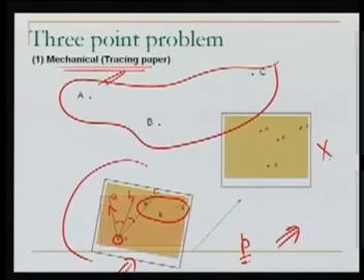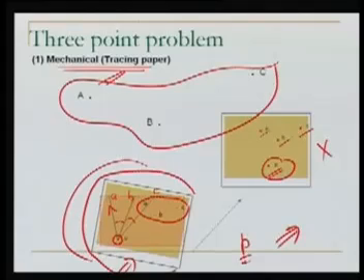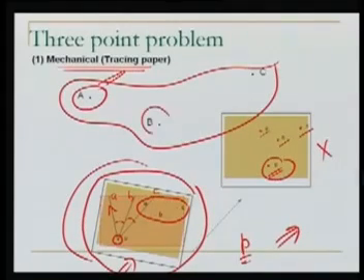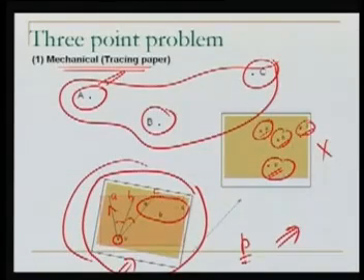We have now A, B and C, which were already plotted on the sheet, and this point P, which we have now found. So basically, what is this small p? This small p is the location of the plane table with reference to our control. It should be here. So with reference to our control, the plane table is located at this small p. That is the meaning of this.